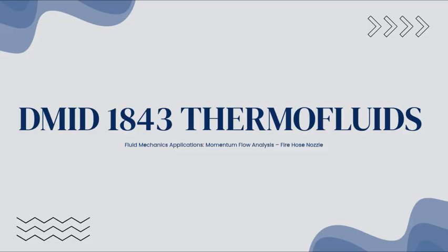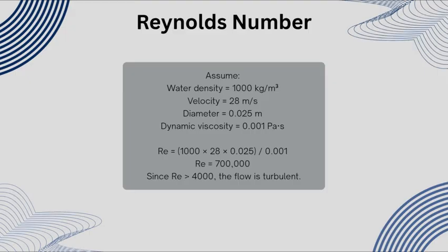I'm going to explain about the Reynolds number. Assume the water density is 1000 kilograms per meter cubed, the velocity is 28 meters per second, the diameter is 0.025 meter, and the dynamic viscosity is 0.001 Pa·s. The Re is 1000 times 28 times 0.025 divided by 0.001, and the Re will be 700,000. Since the Re is bigger than 4,000, the flow is turbulent.